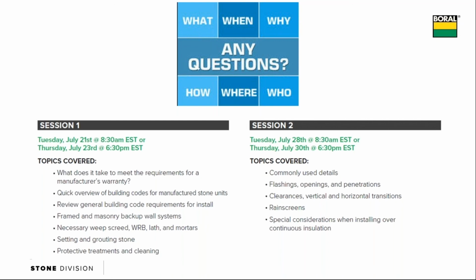give them that look. Conventional mortars like Type S and Type N, when they set that bond and you come in with the next stone and you accidentally tap it just a little bit too hard, it's very easy to break that bond. And so the best thing to do is to pull that stone out, clean it off, and reset the stone. One of the recommendations would be to consider using a modified mortar.